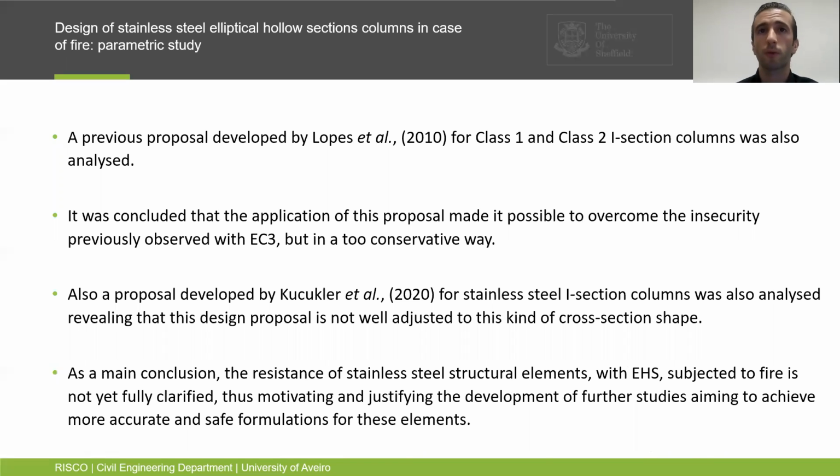A proposal developed by Lopes et al. was also analyzed, and it was concluded that the application of this proposal made it possible to overcome the insecurity previously observed with Eurocode 3, but in a too conservative way. Also, a proposal developed by Kucukler et al. was analyzed, revealing that this design proposal is not well adjusted to this kind of cross-section shape.